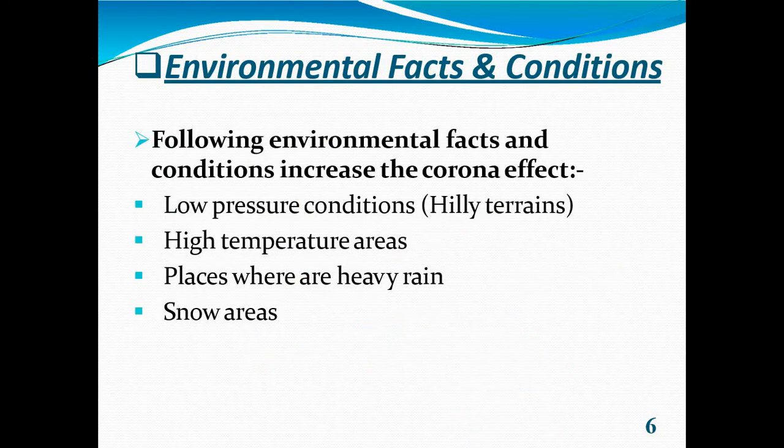Now, environmental facts and conditions. The following environmental facts and conditions increase the corona effect. Low pressure conditions or hilly areas: at low pressure, the air density factor reduces, so the breakdown voltage becomes low, and the corona effect increases.